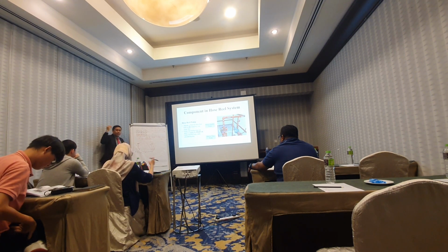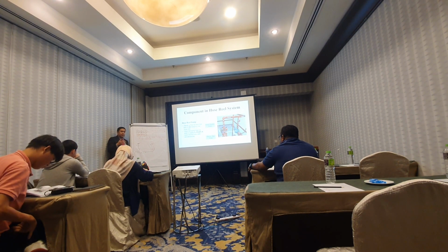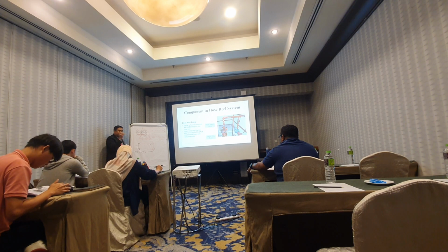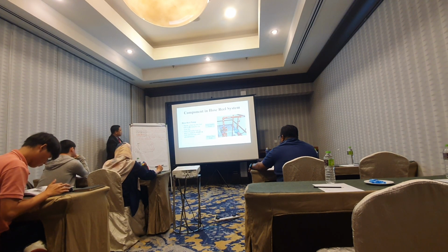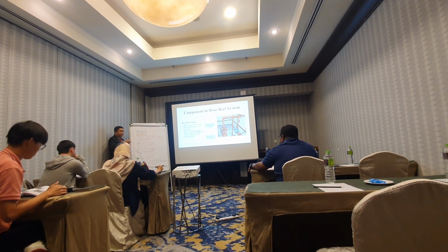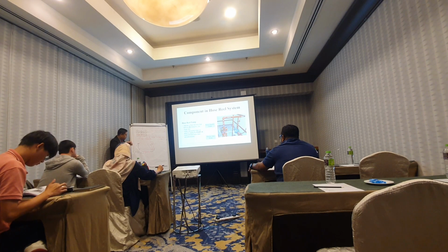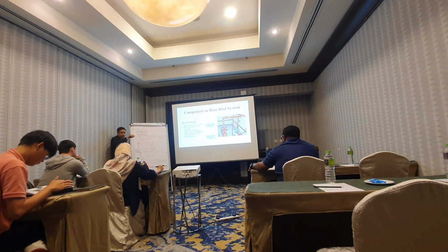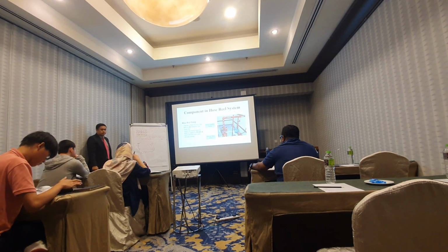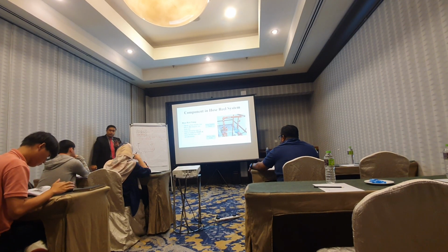Previously, it said a maximum of 9,100 could cater for no matter how many hose reels you want to operate. But here it has spelled out that the hose reel pump shall be able to supply 4 hose reels, right? 4. But if you have designed for 6, you can have more. You size up the tank again, and the pump too. So the maximum for the tank, for 4 hose reels, if you expect 4, is 7,000.